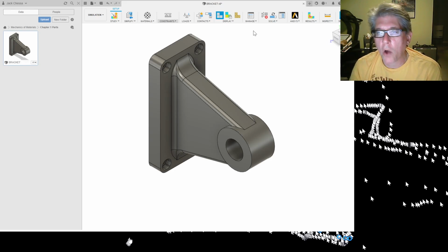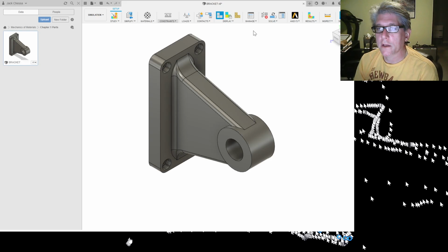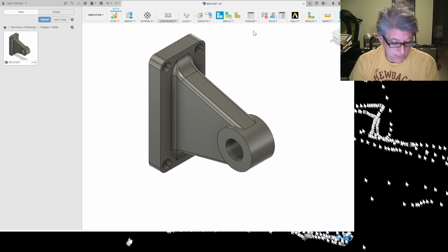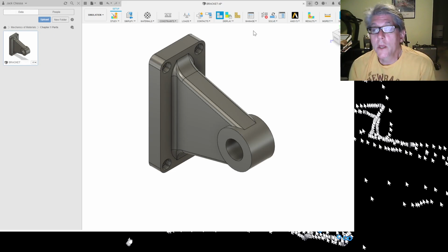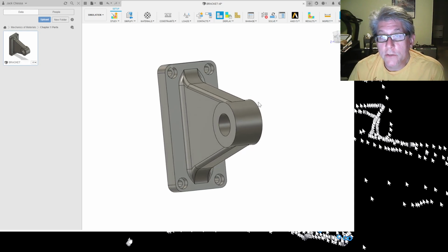So constraints are how we are fixing the body for the analysis. So constraints and loads are what I call boundary conditions, or what most people call boundary conditions when they do this sort of thing. And in fact, these sorts of assumptions of picking the right boundary conditions are absolutely essential to getting a correct or a good simulation. There's a lot of subtlety to it, and we won't go through all that because it's a little beyond the scope of this class, but you do have to be careful about what they physically are doing, okay? So in this case, our constraints are pretty simple, right? We're going to consider the constraints to be these bolt holes, if you will, okay?